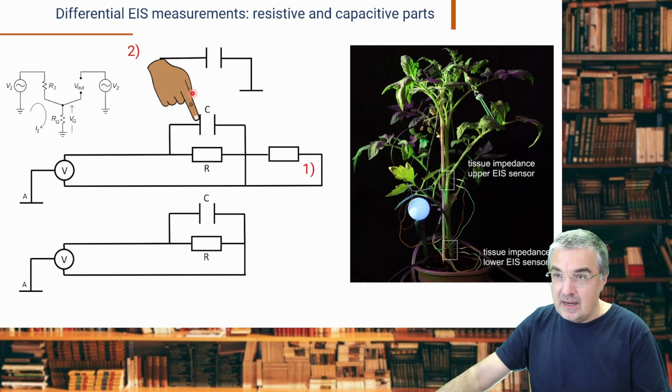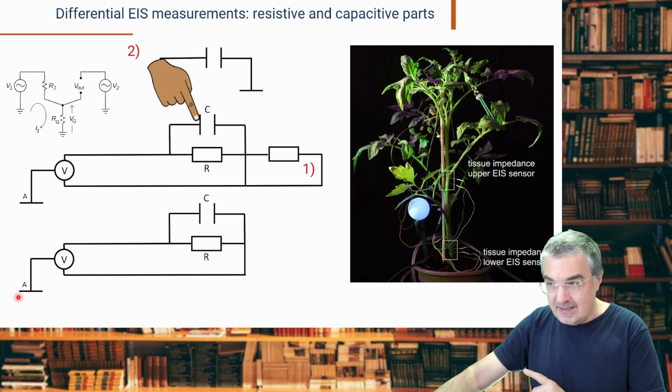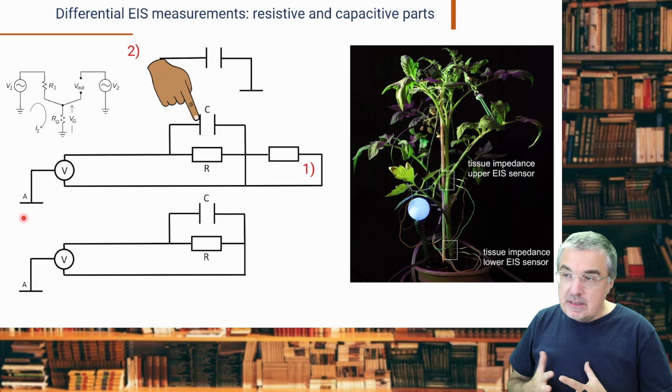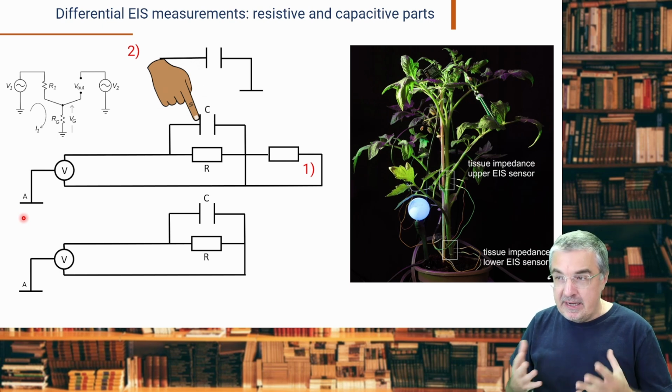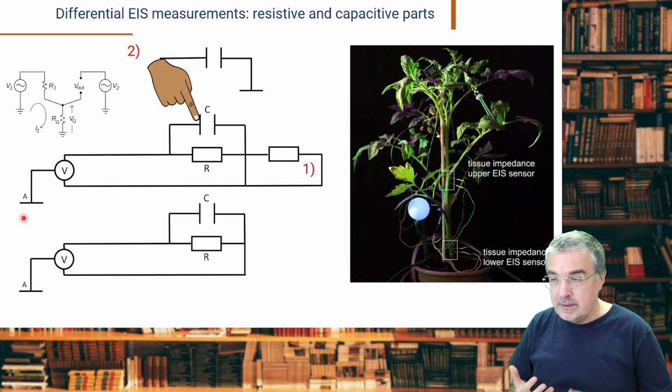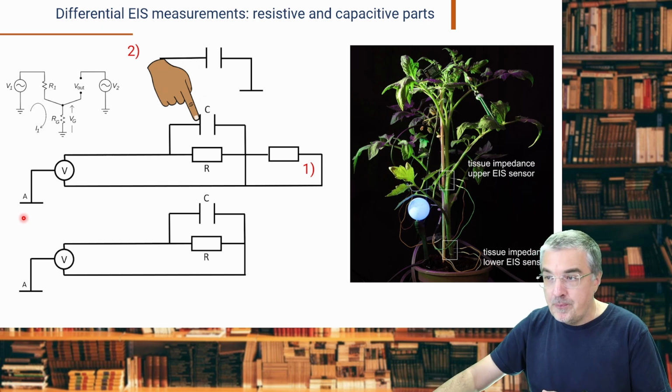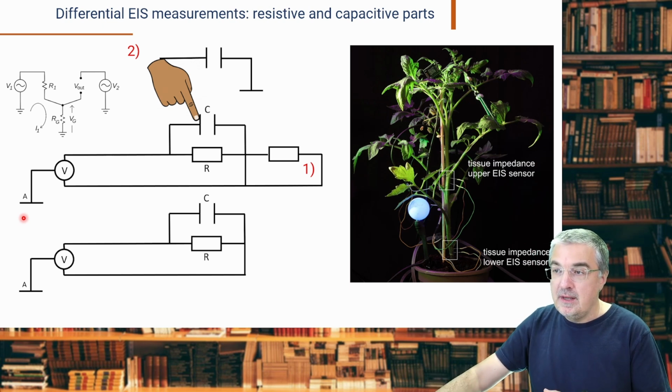So here, by touching, I do not change a measurement. This is important. I do not change the measurement of one channel, but I am changing the measurement properties of the system. So I am interacting now with the analog ground. The question is how to prevent this phenomenon, how to avoid this. Like I said before, we try to decouple the analog ground.